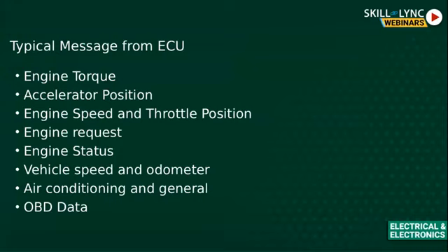So that's about sensors. And as we are going to talk about automotive electronics, we can't skip embedded systems. For you to integrate all these sensors to a controller, your ECU, electronic control unit, is nothing but a microcontroller inside. You have to know there are three types of output that you can expect from any sensor. One is analog output, the second is digital output, and the third possibility is PWM, or pulse width modulation output. Let's briefly see what each of these means.